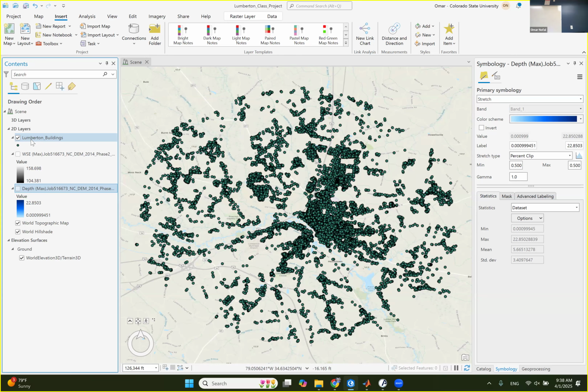I'm gonna give you flood depths and water surface elevation. And you all know how we can use these hazard maps to get the flood depths above the ground and flood depths above the first floor elevation. That's what we need, okay? So I'm gonna give you all this information so you can subtract the flood depth, and from the flood depths, you can get the other information.